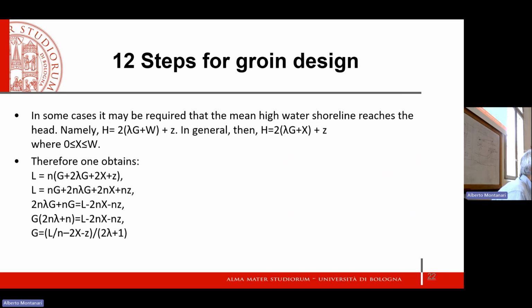You may remember that I anticipated to you that a gap that is lower than 20 meters, to give you an example, is not good. It's not good because you get the feeling like you are in a prison, you go on the beach and you see the series of channels and it doesn't look like a natural environment. So it's not advisable. In the same manner, it's not advisable that you displace the groins at a distance that is larger than, say, 100 meters, because otherwise, they become a kind of sequence of isolated interventions rather than a combined set of measures. So especially if you see that the situation in the critical zone is tightly interconnected, it's not the sum of some local singularities, then in this case, it's better that you don't space the groin beyond kind of 100 meters, okay?